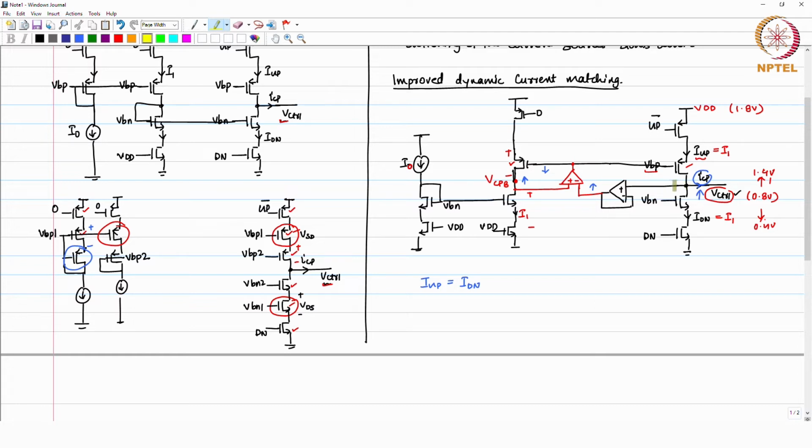Any change in the control voltage activates this particular loop, and it is changing VB here. For example, if the control voltage increases in a steady state, every reference cycle you have some current which is added to the loop filter. So, if the control voltage increases, this particular loop also acts and it responds to local disturbance.